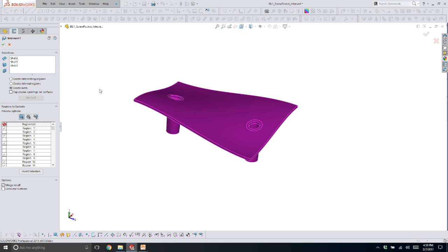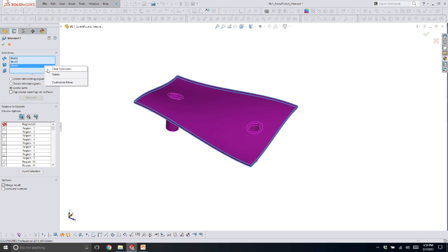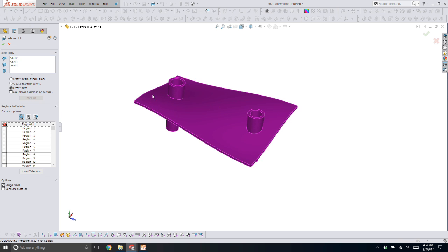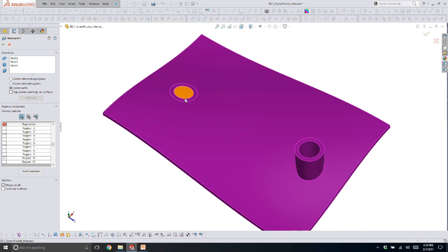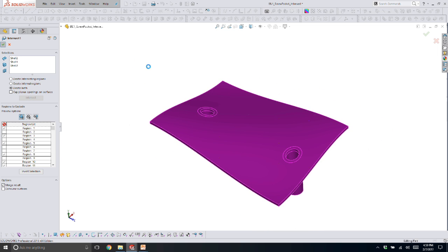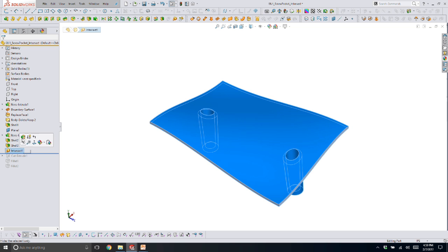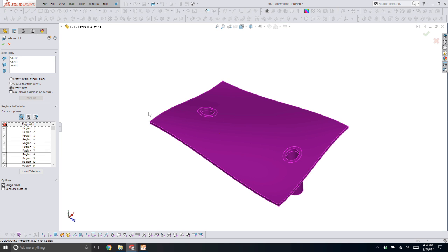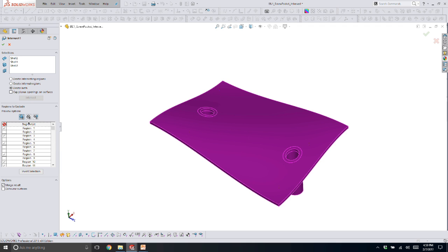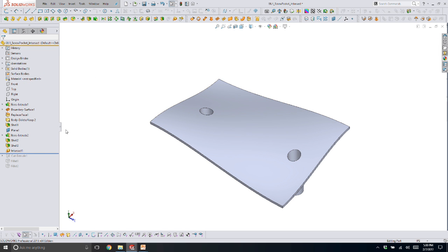Not entirely certain. I pick the bodies that I want. We'll just demo this. So I'm going to grab this. We're going to intersect. And now what I do is I pick the stuff I don't want, and you can see that the graphics preview goes away. So you just pick the stuff you don't want, and click OK. You're good to go. If it was easier for you to pick the stuff you actually want, because there's a whole bunch, you can just pick stuff that you do want to keep, even though it says region to exclude, and then invert selection, and then it gives you all the stuff you want. Finally, I'm going to clean up the sharp edge here.